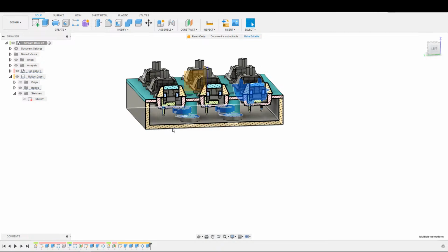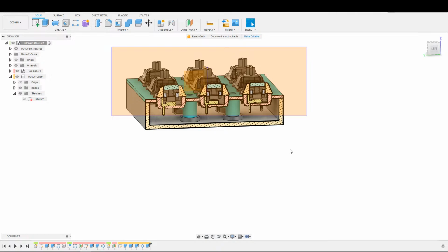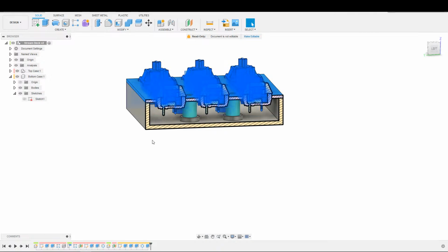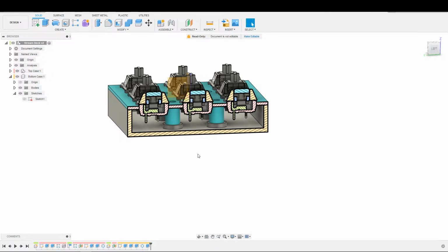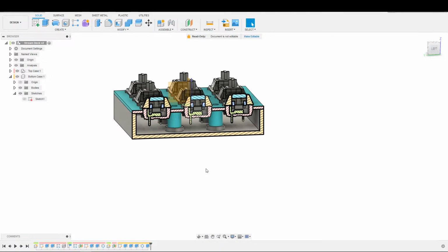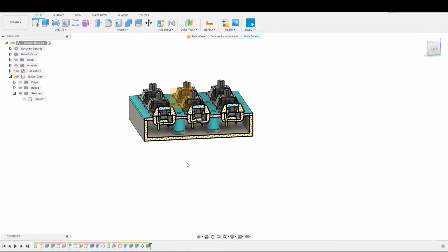I'm just thinking through the ramifications really quick. So if we add another component completely down here to attach the rollers to, that will get printed a lot easier than if we try to print this with the rollers down here on the bottom. These rollers overlap the top half right here on the next one above it. So if we print it in two pieces, that prints easier. And it allows us to not print the rollers for the bottom one, which attaches to the base that has the Arduino on it inside of it. We don't need the rollers on the bottom one that is attached to the Arduino. So we're not printing any extra, is what it means. Yeah, okay, so that's everything we've got to consider. So let's get that implemented.